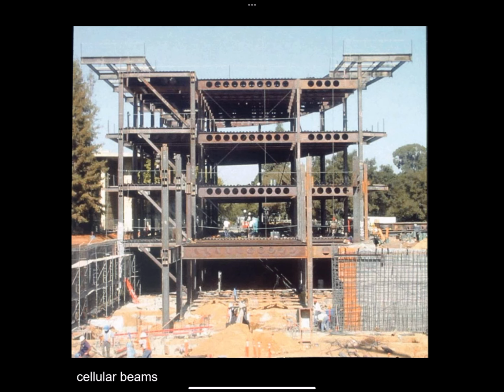So with steel structures or concrete structures, anytime you want to make a big hole in the structure for something like an air duct, your structural engineer is going to get rather nervous and is going to limit what you can do. So something like the castellated or the cellular beams mean that we can freely run services through these holes.